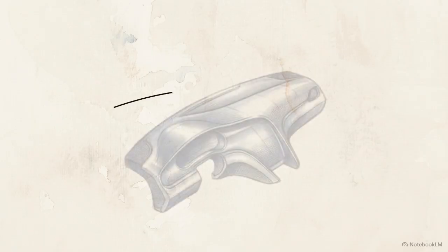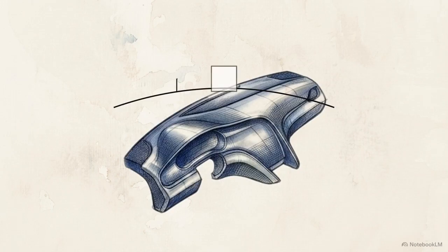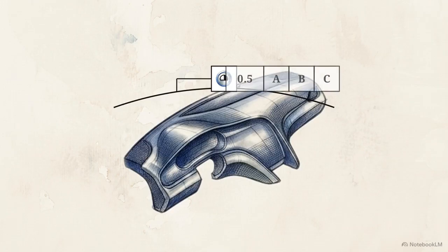When drafting, a common mistake is selecting a position tolerance to control a complex surface. Position is intended for features of size like holes or pins. When you need to control the functional boundary of an actual surface, profile is the correct tool.